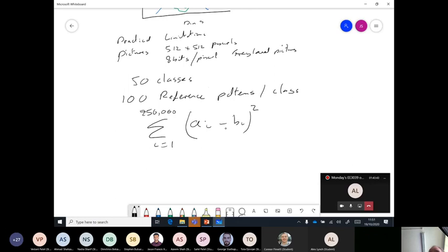We've got a subtraction, which is the same as addition in terms of processing time, but we've got the squaring operation, which is a multiplication. From your assembly language knowledge of level 1 and level 2, you know multiplication takes a series of instructions. It's much longer to implement. It's a shift and add process, at 8 bits resolution. It will take a lot longer than the simple addition.